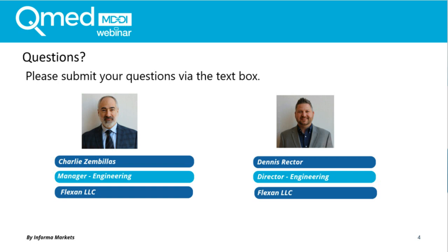Our next question asks, when extruding striped tubing, does this affect the burst pressure rating? There again, we would leave that up to our customer's final design verification testing. However, generally, barium stripes don't affect the integrity of the silicone tube. It becomes cross-linked to the clear material and part of the extrusion, just like if it was all clear. All right, thank you, Dennis.